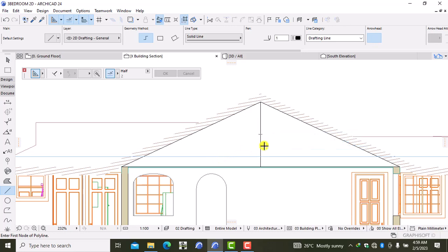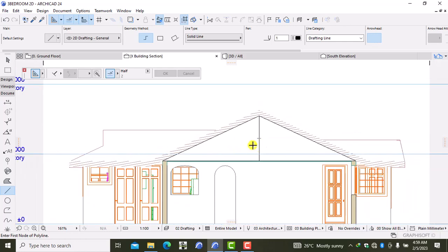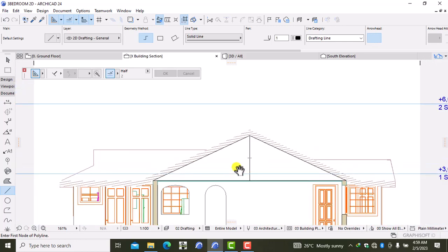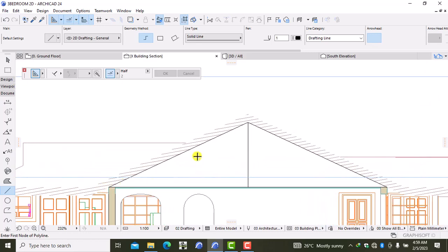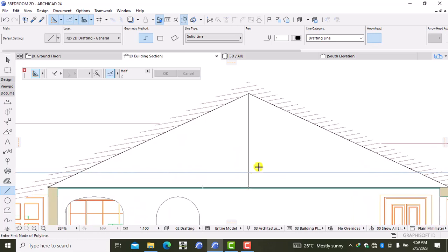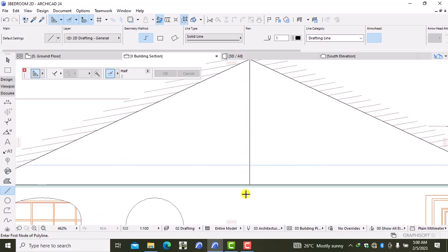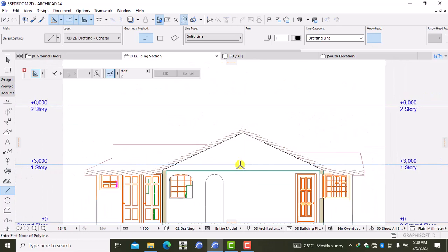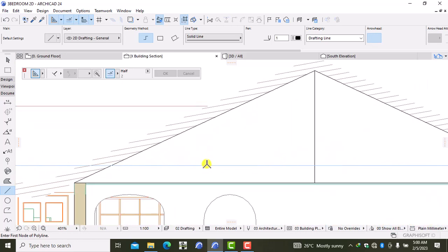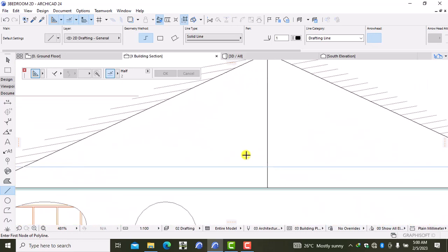I can also decide to use arbitrarily fixed values for the sizes of the trusses right now, because we only just need to do a sketch of the truss. We are going to give the fine details in terms of the size of the rafters, the purlins that should be used, the roofing size and such. So basically I'm just coming up with a sketch of a typical truss that will be used while doing the roofing of this house.